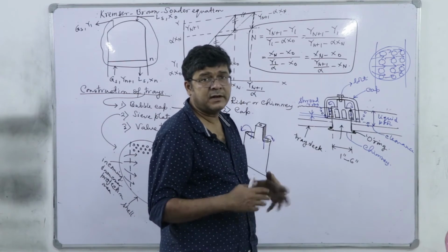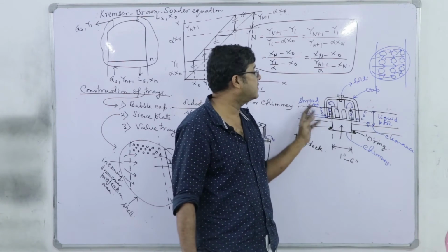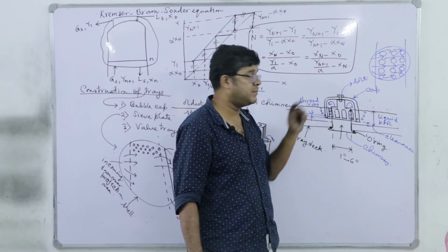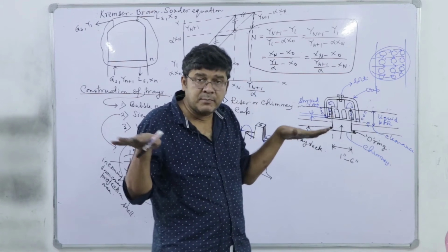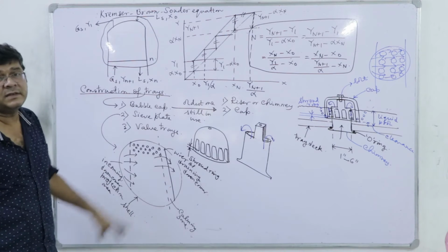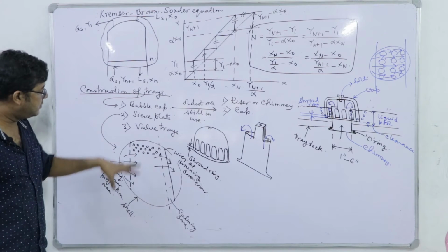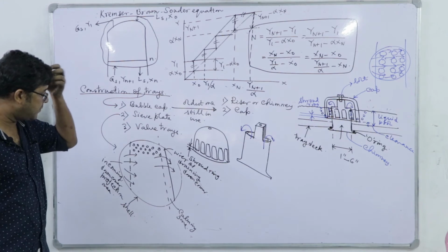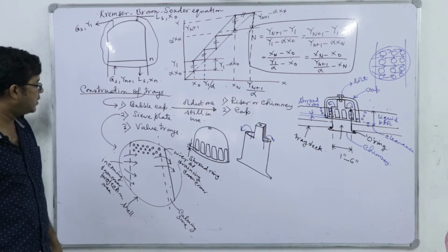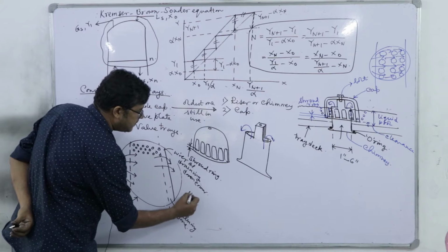So weeping of the liquid, which is a non-ideality, that means whenever the gas pressure decreases, the liquid may weep, but in bubble cap it will not weep if you have maintained a definite hydraulic gradient. But that may be a problem in sieve. Though you are saving a capital cost, you are allowing this weeping if you have low gas velocity. Generally, these sieve holes,